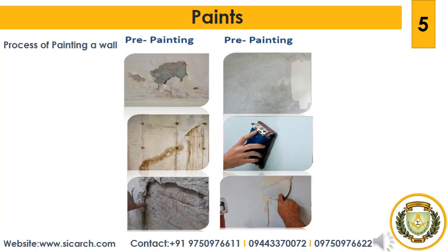The brushes should be composed of bristles and not of horse hairs. The bristle brushes are elastic and possess good paint holding capacity. The bristles have split ends and in this respect they can be distinguished from horse hairs. It is preferable to use a round brush in painting. The new brushes should be soaked in water up to the level of bristles for a period of about 2 hours and then they should be allowed to dry for a period of about 1 hour.